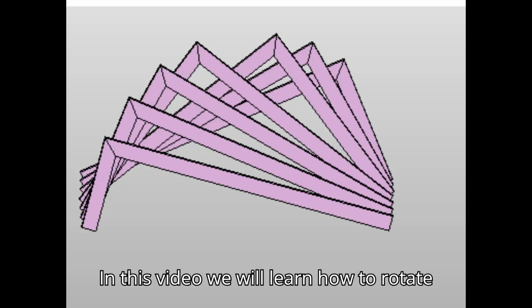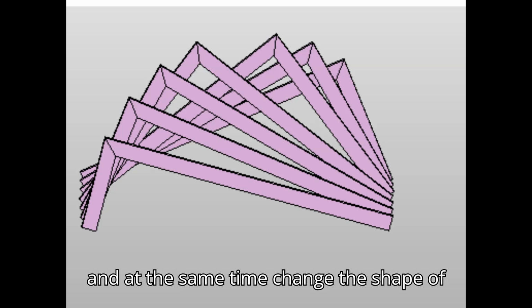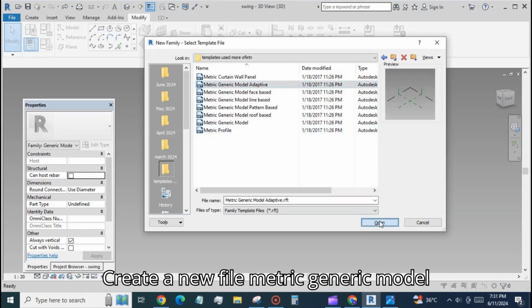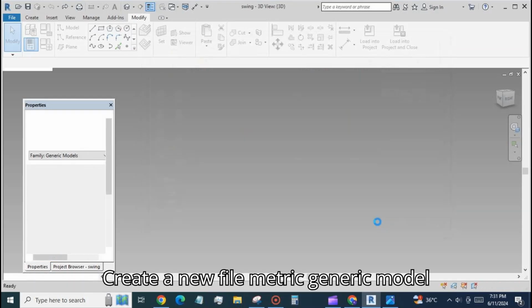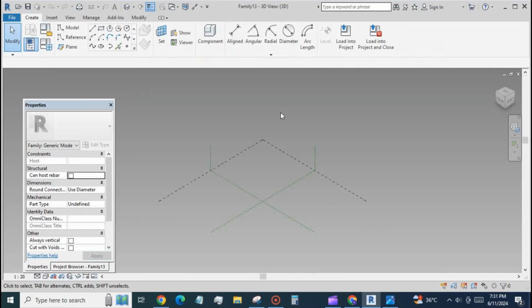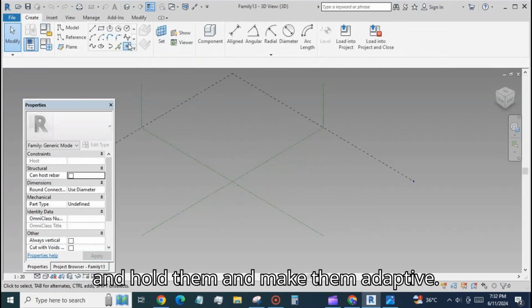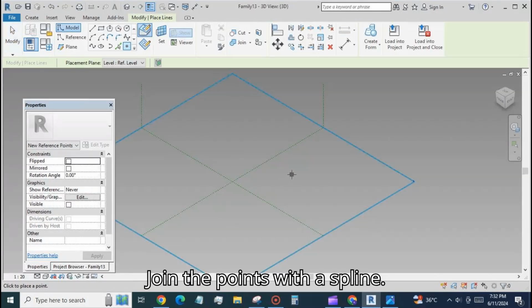In this video we will learn how to rotate and at the same time change the shape of an angular form. Create a new file metric generic model adaptive. At the reference level place 2 points and hold them and make them adaptive. Join the points with a spline.